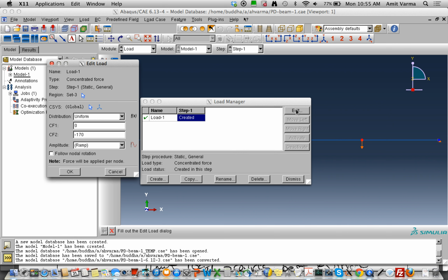If I wanted to push it further out, if I wanted it to go all the way, then what I would do is instead of applying the load, I would apply a displacement boundary condition, which means that I would select that same node, but instead of applying a load, I would apply a U2. And I could give it any U2 I wanted. I could tell it, all right, take this point that's located right here where the loading is being applied. Take this point and subject it to a U2 of 1 inch or 2 inches or 3 inches or 4 inches. I'm not specifying a load. I'm doing the analysis in displacement control. I'm telling it push it all the way to 2 inches.